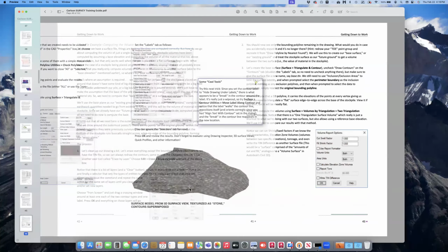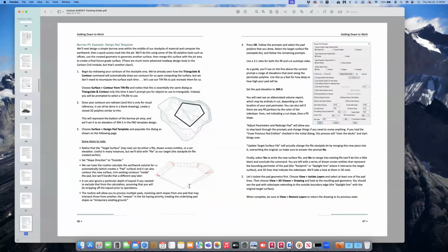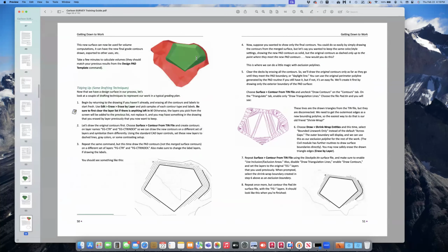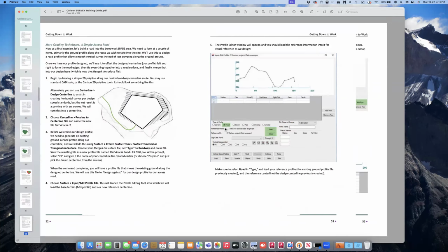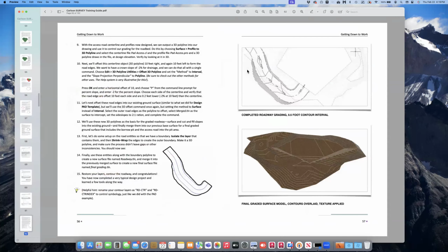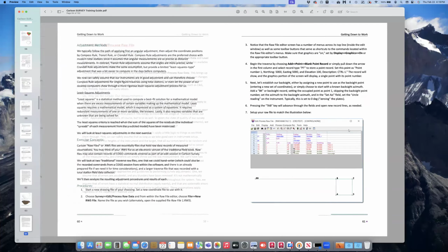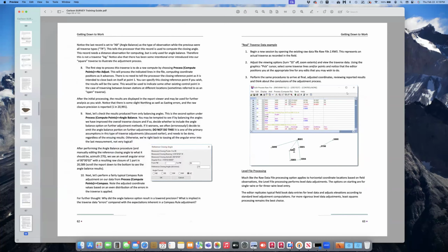We'll make a group out of them, a group out of the interior points, and then we're going to generate the terrain for that, and then design a borrow pit to be able to cut out a particular amount of material that we might want to take out of that, and then generate a little haul road to come up into our borrow pit and go from there.